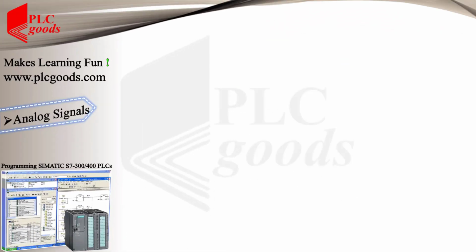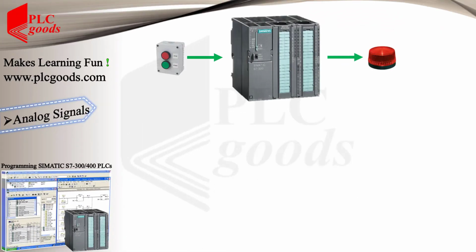Let's start the video. Until now, we have done some projects with digital inputs and outputs. At the beginning of this tutorial, I explained my PLC hardware and also its wiring. We know digital sensors or push buttons have two states, on or off, open or closed. These devices can use 0 and 24-volt DC to send their status to the digital inputs of my PLC. Also, the digital outputs of my PLC use 0 or 24-volt DC to turn off or on a digital actuator such as this signal lamp.